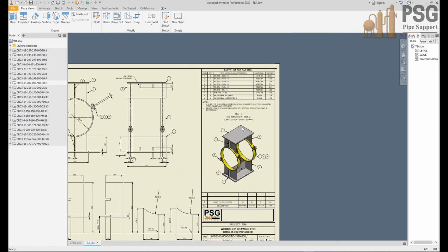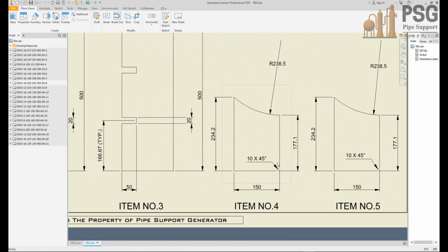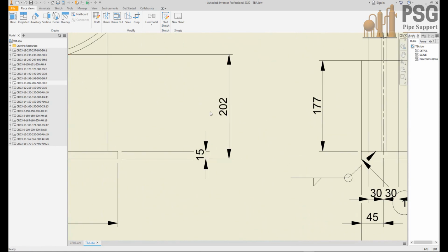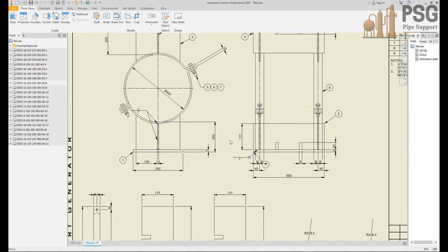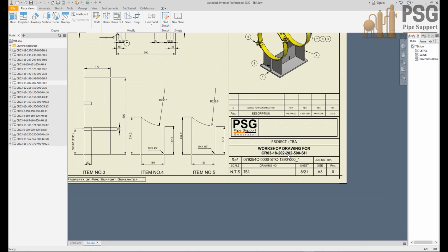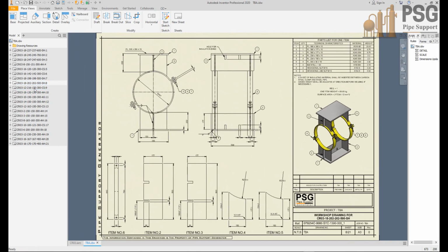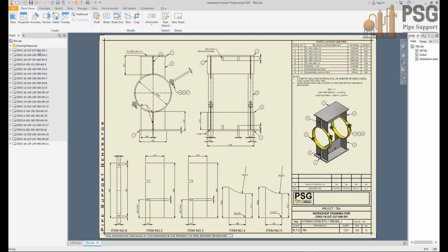weight and surface area. Pick the number of the sheet, the dimensions of each element, the height for top and bottom, and as mentioned, they should be identical with the support marks values. Okay, that way you can collect all drawings in one sheet. After that you can print in DWG or PDF or DXF, so you have different ways to export your drawing.